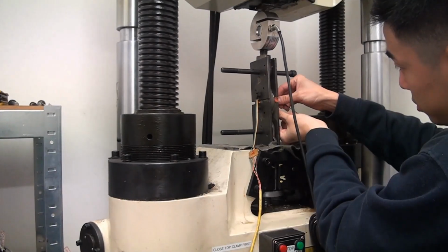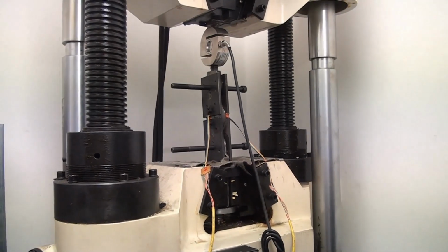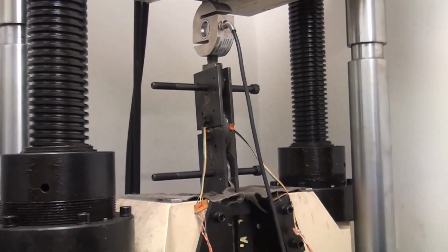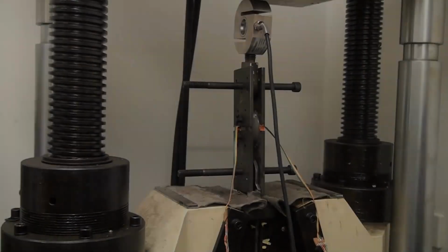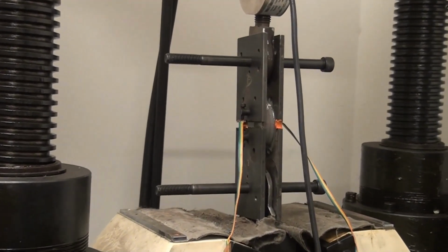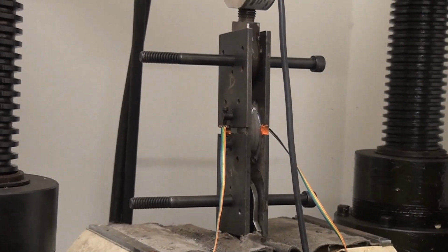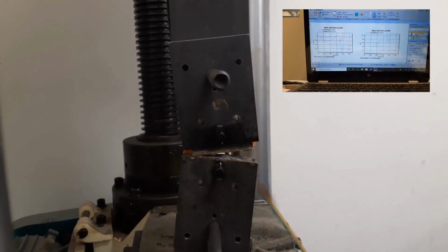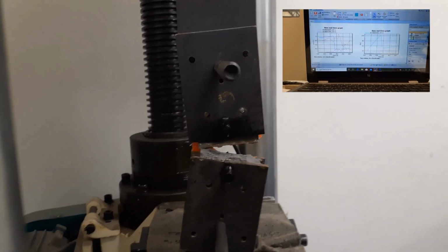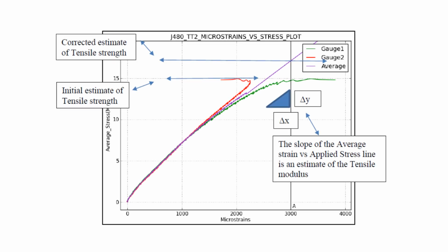We pay attention to the tensile behaviour of some rocks, as these frequently control goaf or caving behaviour or the nature of rock bursting. This video shows the testing of a rock sample that has been cut transversely across a 61mm core in the form of a 15mm thick biscuit-shaped rock sample. The sample is glued between steel plates and is then loaded. The deformation of the rock sample is measured on either side of the test plates to ensure that loading is evenly applied. This shows an example of the results of a transverse tensile test.